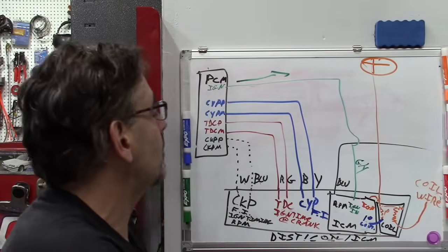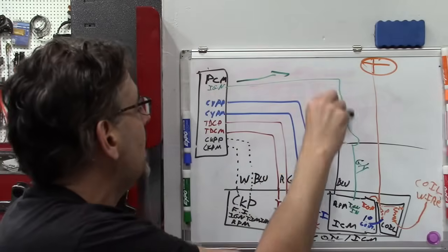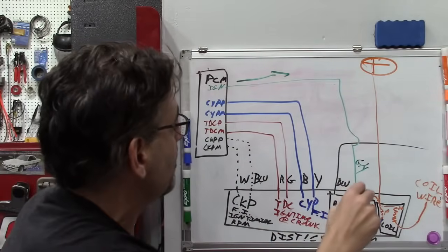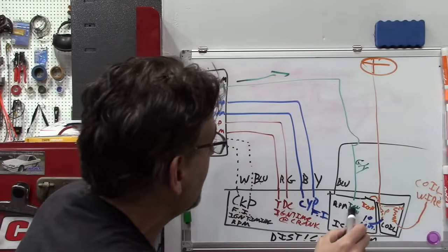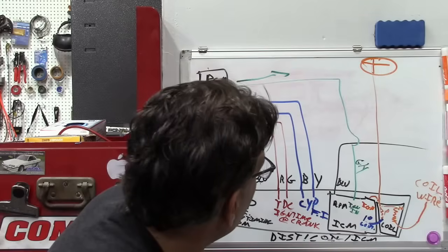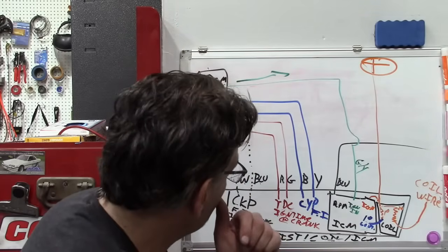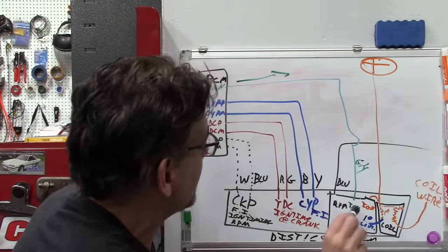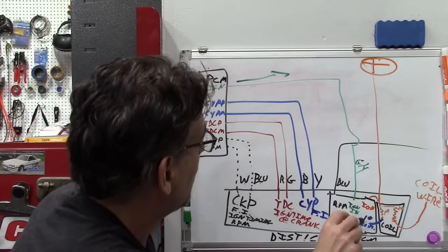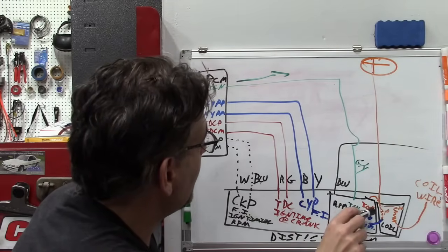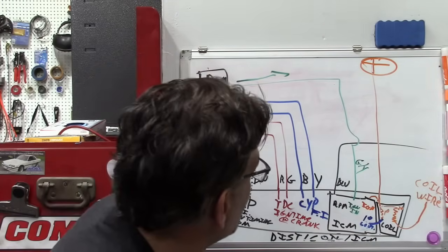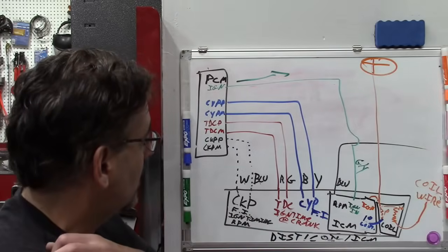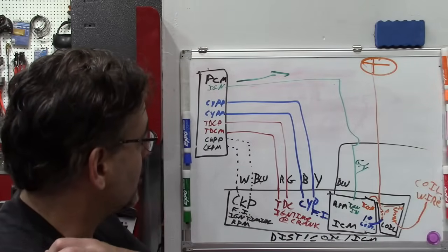We also could have a variable where there is more necessary in this system than just this ignition input, but I don't think so. It does look like the ignition output to the coil may have some control from the ICM, and the ICM may be using some different inputs, not shown on here.